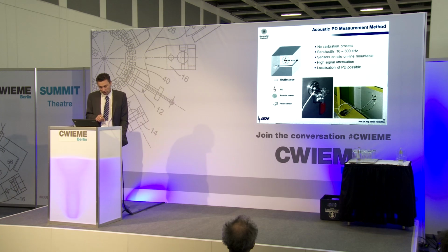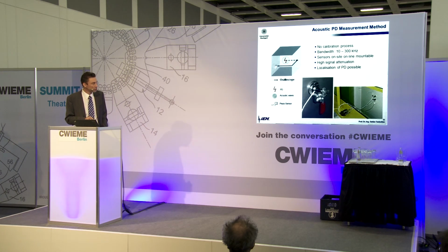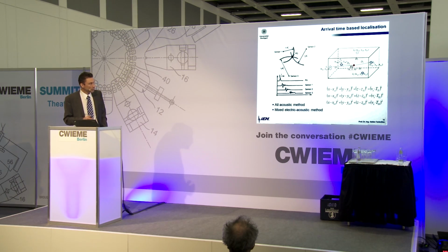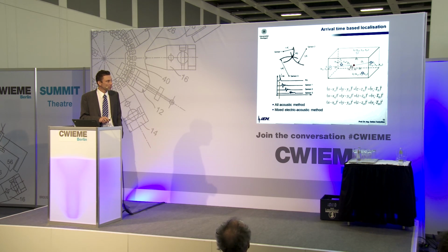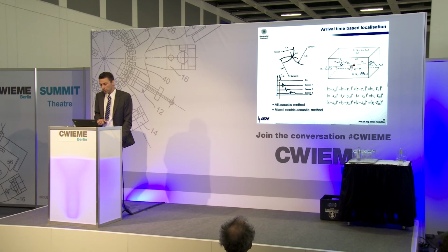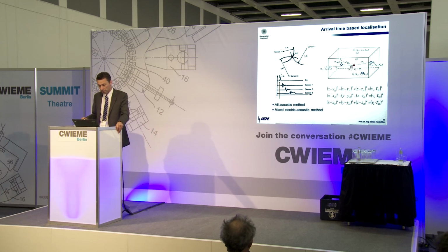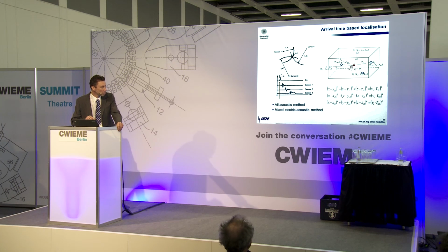So problematic is the high attenuation of the signals. One benefit of acoustic measurements is that by measuring the time which the acoustic signal needs from the PD to the microphone, you can do a localization of the partial discharge. For this you have to install several microphones on the transformer tank, and then by solving these equations you can localize the PD. I will show you later one example where this was done.